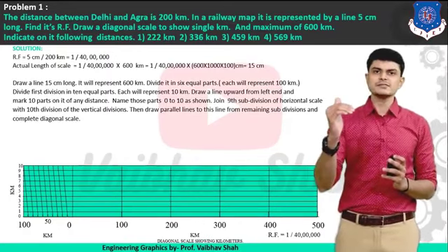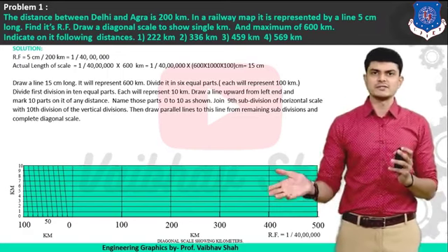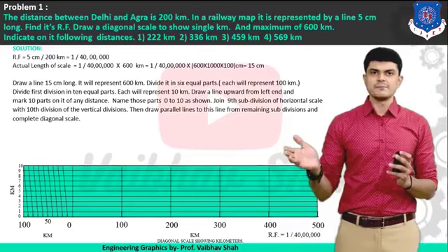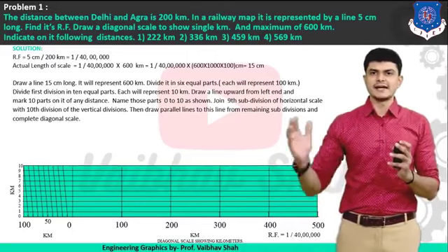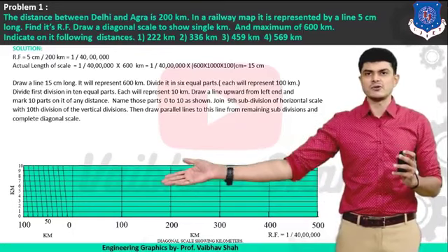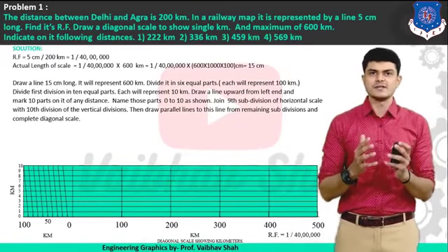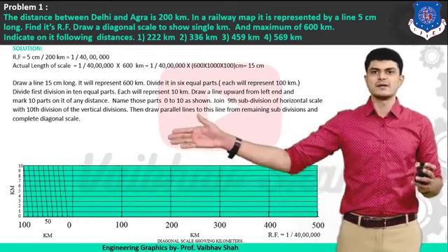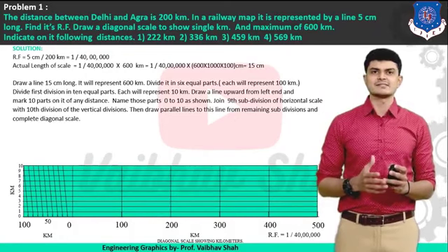We have 3 scales, so that's why we have divided this 569 into 3 different units: 500, 60 and 9. First of all, we will measure 500 on the primary scale. 60 will be indicated by the secondary scale, on the horizontal line, and the third, which is 9, will be indicated on the diagonal scale, meaning your inclined line. So let us start indicating your 569.